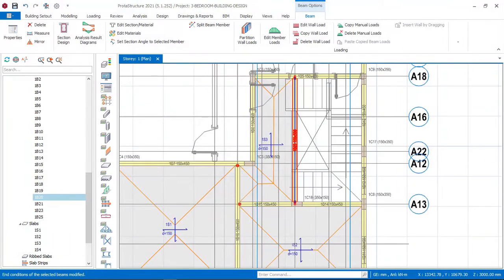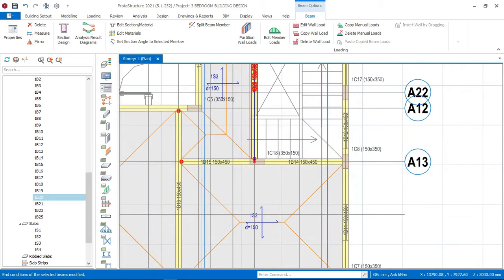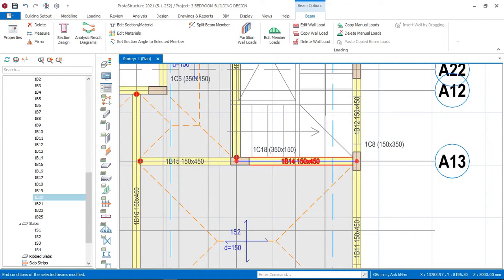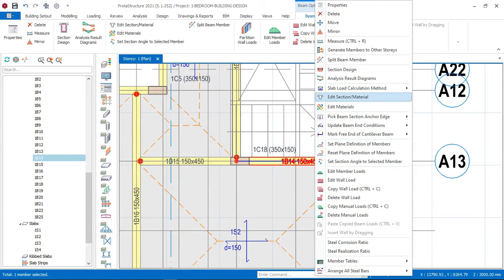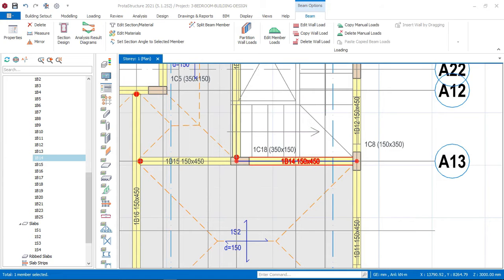But normally, as we all know, even in theory, the moment value at every end is always zero. So because of that, right now we are trying to free all the ends of beams not to have moments, because that is how it is meant to be. So that's why we are applying all these hinge ends.